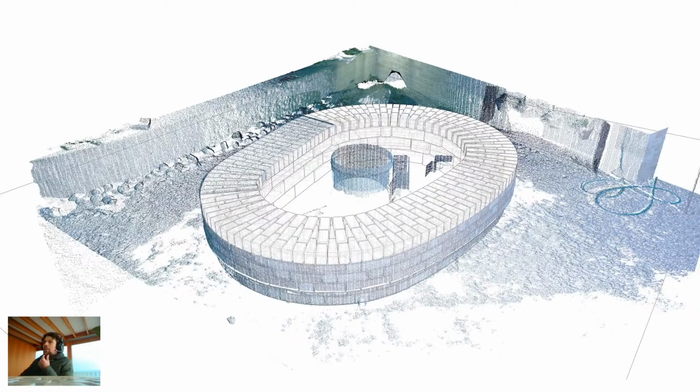We're always asked by anyone in these sorts of talks and presentations how accurate the HoloLens is, and it's a really difficult question to answer just because it depends so much on the care and the precision that you're taking when you're following holographic guides. But in the case of this brick project, we were pretty careful to do a fairly rigorous empirical analysis of the precision of the HoloLens by building a prototype and 3D scanning it. And we were then able to compare the 3D scan to the digital model to work out exactly how precise it was. And we published a paper on this if you're interested in looking into it further.